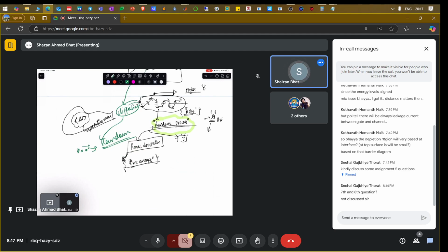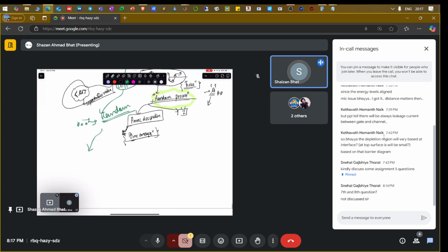Okay, and when you write the diffusion equation for the electron, how do you write it? Let's write a rate equation, something like dn by dt is D d squared n over dx squared, plus some generation minus the recombination. So you have a diffusion coefficient here.